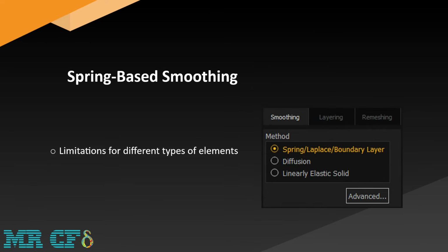Finally, here is a summary of the capabilities and advantages of the spring smoothing method. This method is used to update any cell area whose borders are moving and changing shape, but for non-tetrahedral or non-triangular cell regions, this method can only be used if either the border of the cell region moves mostly in one direction or the movement is mostly perpendicular, because if these two conditions are not met, the resulting cells may have a high skewness value.